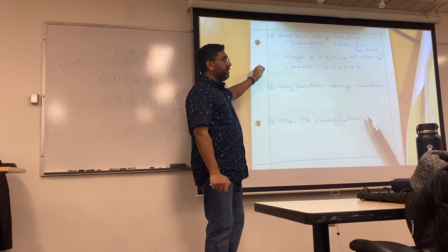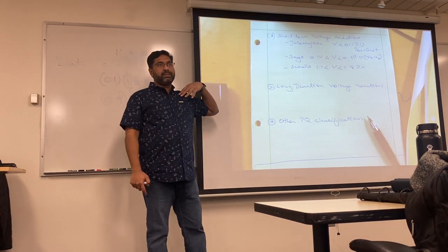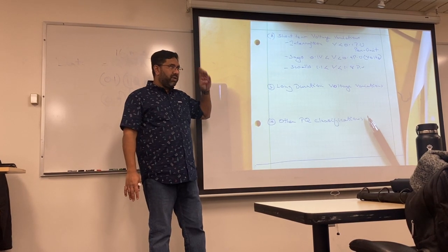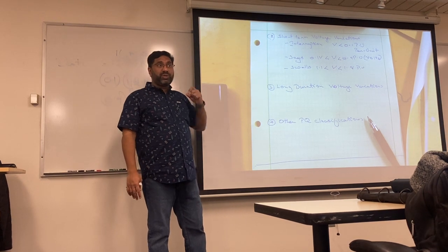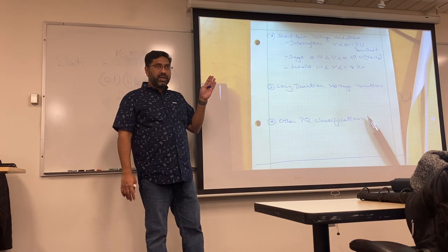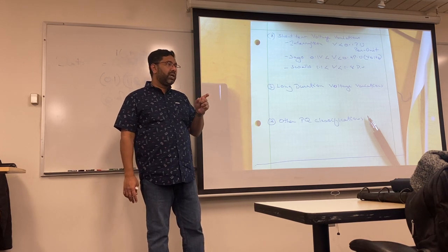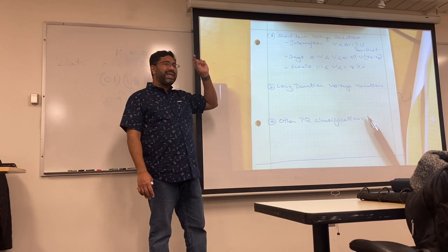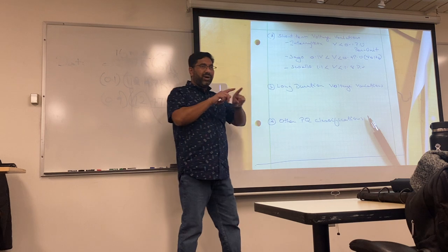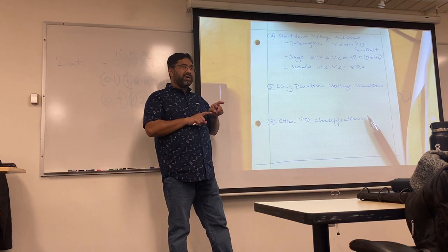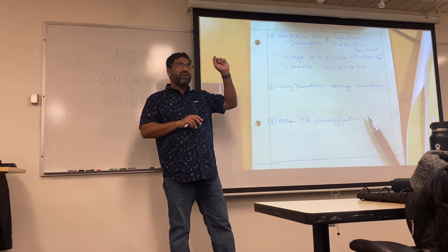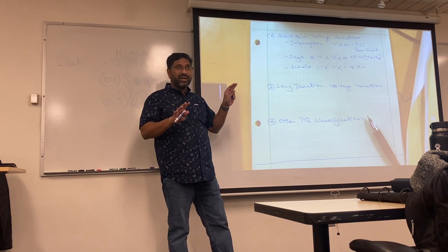So imagine this. You have a 3-phase line and a short tree branch just falls on that. We do not want to be in a situation where we are taking down thousands of customers for no good reason. So a short-term duration is you had a fall, but it sort of cleared away by itself. But for that particular moment, there was a voltage drop because 2 lines shorted or there was a voltage collapse. So if a tree or a branch falls on one of the lines, there would be a short-time duration. You'll probably see some sort of flicker, but that's about it.